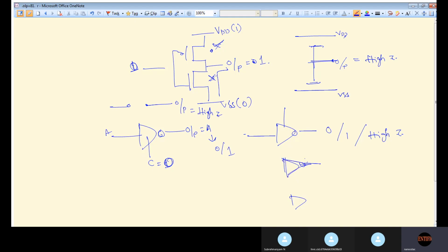If I am taking an example of buffer, this is A and this is B and you have C, D. Okay, so ఈ కనెక్ట్ చేసి మళ్ళీ ఇంకొక బఫర్ కి ఇస్తున్నాం. ఓకే, సో these are the tri-state buffers. ఈ ఫస్ట్ రెండు tri-state buffers. ఓకే, సో this is the Y you are getting. ఇక్కడ చూడండి, when C and D are equal to 0 and 0, what is the Y you are getting here? Y ఏమొస్తుంది చెప్పండి?